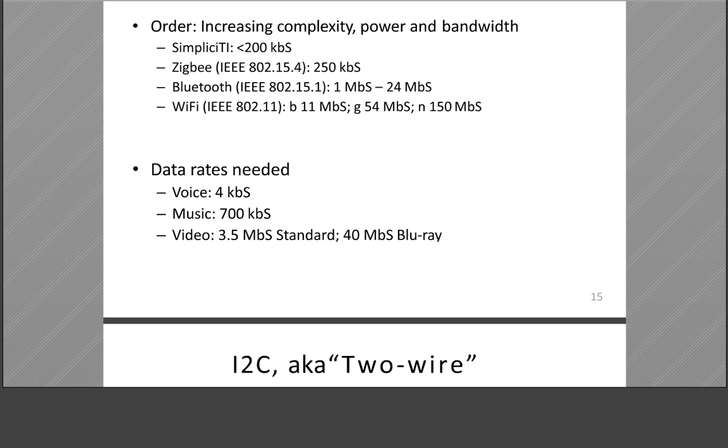What's the correct sampling rate in A to D? This is the result of the Nyquist rate. Nyquist was a scientist, who says the sampling rate must be greater than twice the maximum frequency of the signal. Okay, Nyquist rate or Nyquist theorem for sampling.